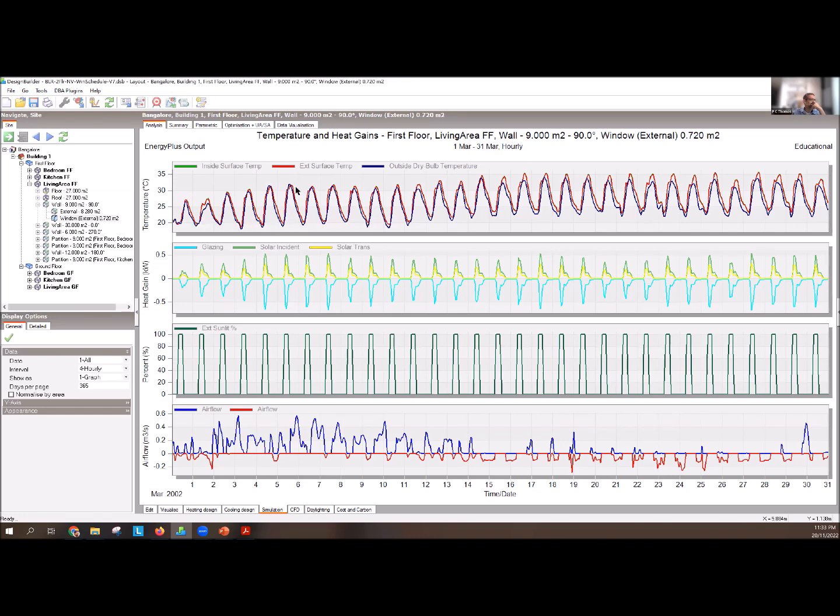It's clear glass. There's no reason for you to expect any differences. If you were using a high performance piece of glazing, which was double glazed, then you'll see differences there. It tells you what's happening in terms of how much solar radiation's hitting the window, how much is going through, etc. What percentage of that window is sunlit at what time.